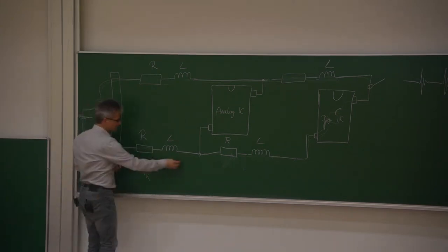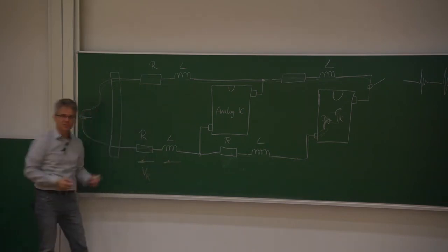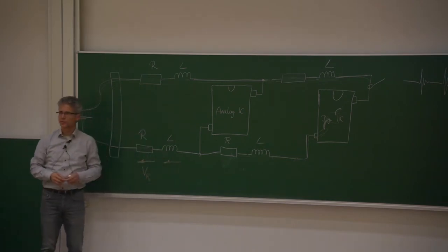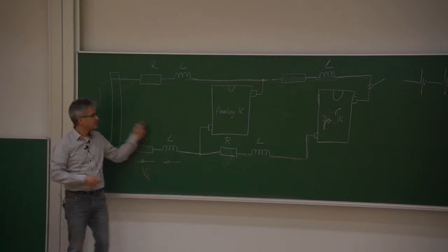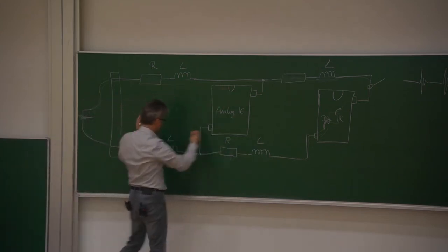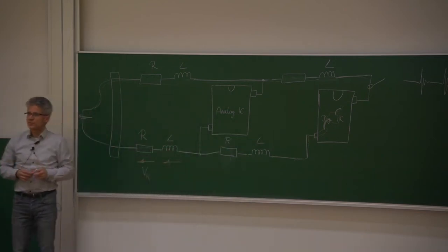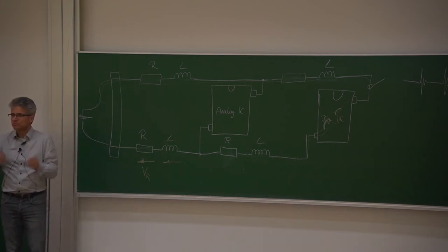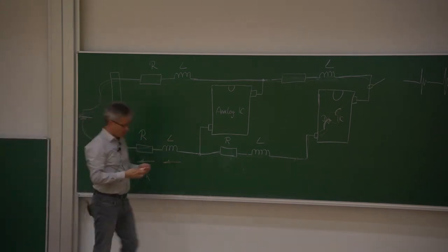But here comes the point. In series to this resistance, in this very simple equivalent circuitry, we have an inductance. We said the whole inductance is 1 microhenry, so maybe this part here is 25 nanohenry. Good guess. And now we have a big di over dt.